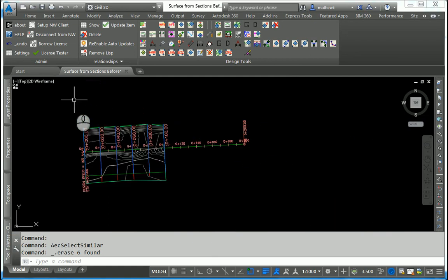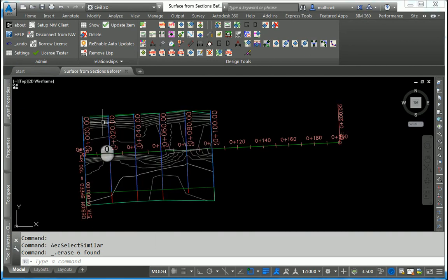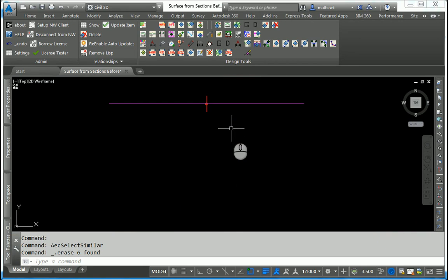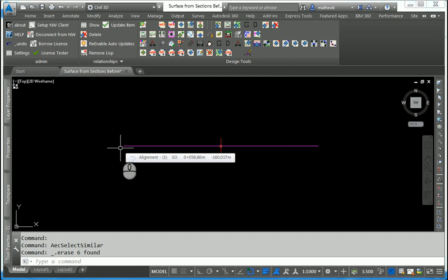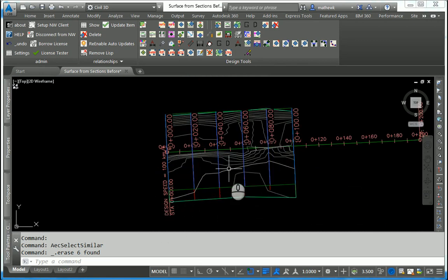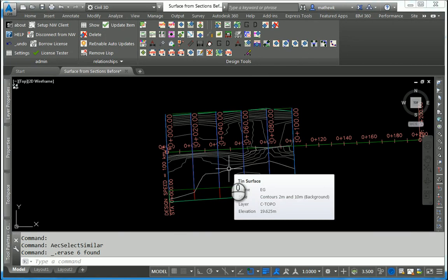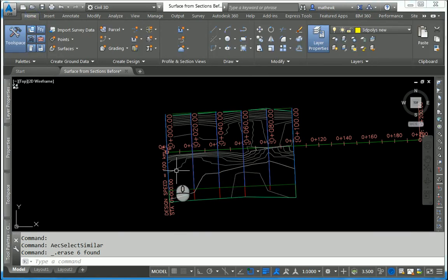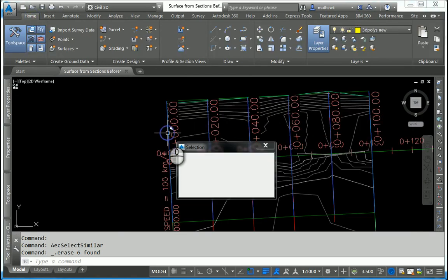So this lesson assumes that you know how to make a corridor. So there's my basic surface. I have an alignment that goes up the center, and I just have a basic corridor. There's my assembly. In this case, it's a 30-meter line to the right and a 30-meter line to the left. When I go into View Edit Sections, I'll see 60 meters of my surface. Then I built the corridor. So again, it's a flat 60-meter wide corridor. Now the trick here is